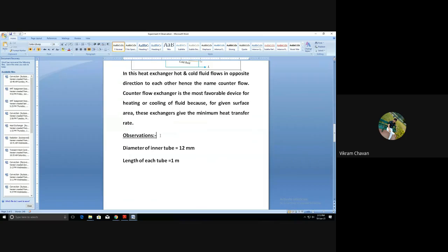So that will provide you the surface area. Okay, so pi d l will be the surface area, and the calculations are on the basis of inner surface area. Inner tube diameter is provided, so we have to consider all the calculations on the basis of inner surface area, with suffix i, and that will be required for the calculation of the overall heat transfer coefficient, that is U.